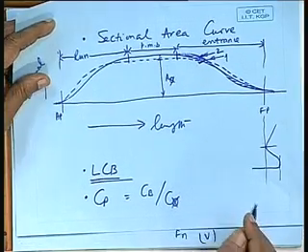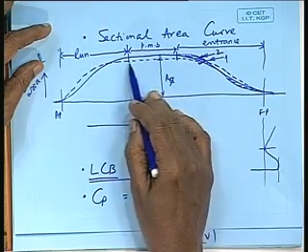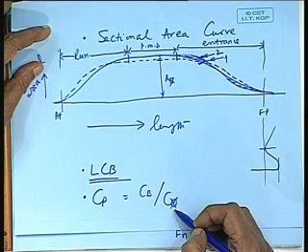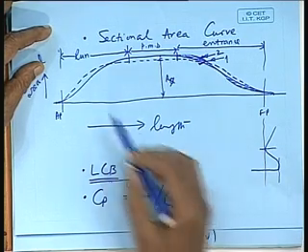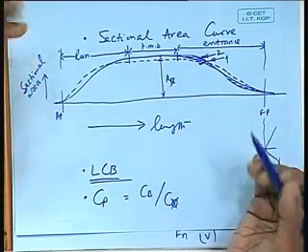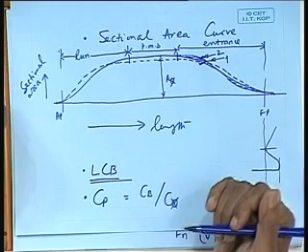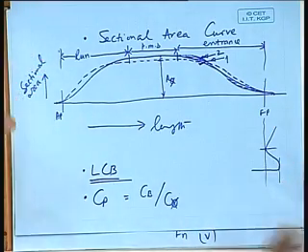Right. In these two cases, you can see that Cp for the dotted line case is higher because C midship is lower. So, this dotted line, that is lower Cm or C midship, lower midship area coefficient coming out of larger bilge radius, will give me higher Cp, and this is having lower Cp.